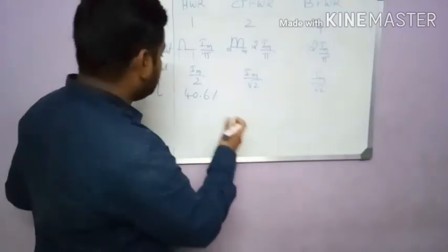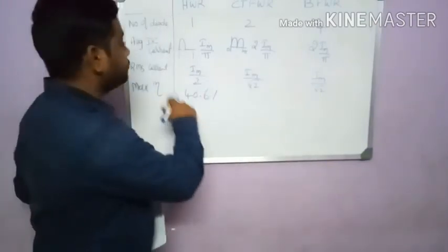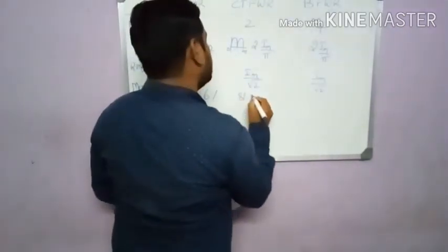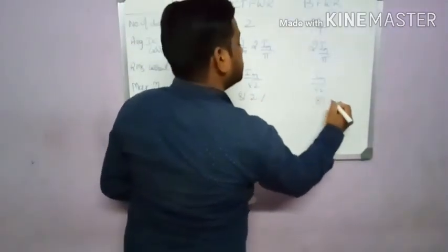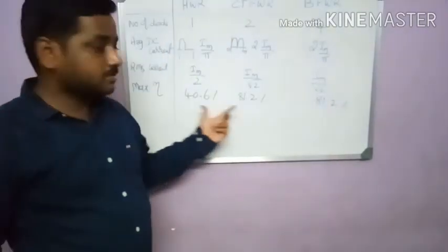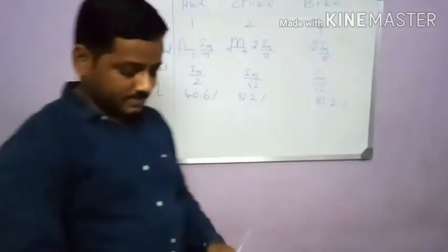And for full-wave rectifier we get 2 times of this, because we get 2 pulses, right? So 40.6 plus 40.6, 81.2%. So now comparatively I can say that full-wave rectifier is lot better than this. Its efficiency is higher. That's good, right?